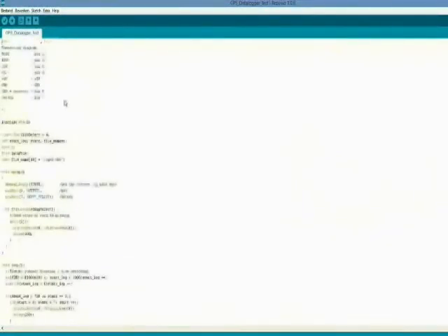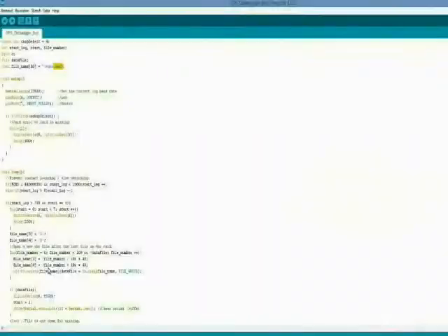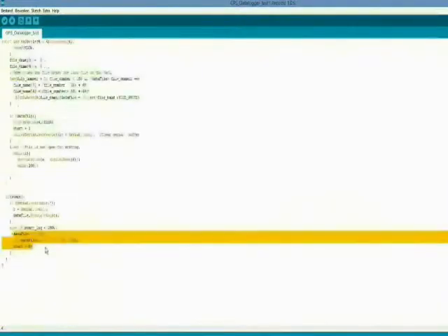Gate level simulation methodology: Verilog simulation with back annotated delays, VHDL simulation, VITAL compliant VHDL models, and back annotated delays. Verification tools supported are Avanti, Polaris, Cadence Verilog XL, Leapfrog, ICOS, Mentor Graphics ModelSim, QuickTurn, and Synopsys VCS, as well as Vera.